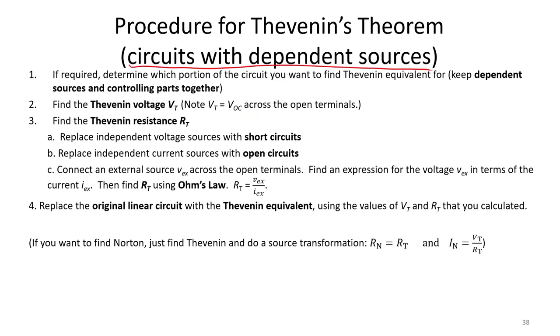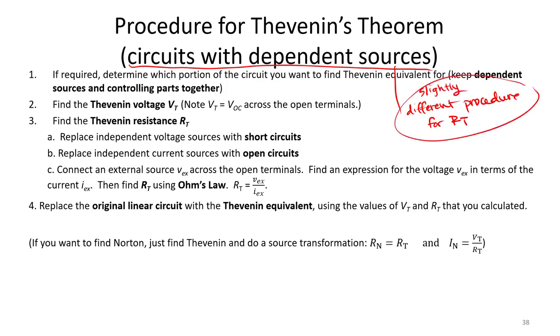So make sure that you follow the correct procedure for finding Thevenin resistance. Again, be careful. Slightly different procedure for Thevenin resistance with the dependent source.